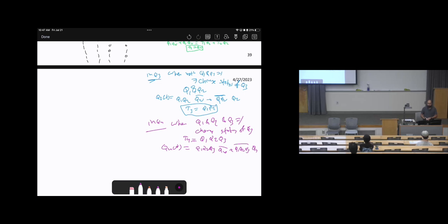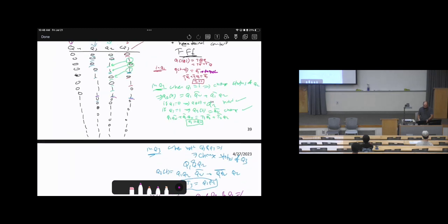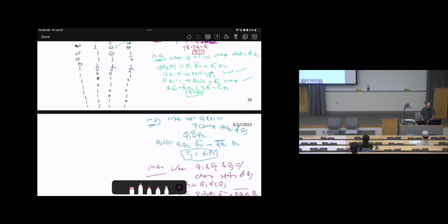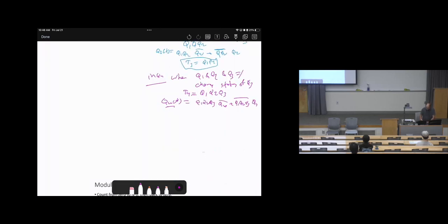Okay, so what else? How can I draw my design? Now, I already assigned all of these four. Now, I need to make my design. Again, it's based on 4 T flip-flops. So let's draw these 4 flip-flops as shown here. Here is first one, second one. Let me make some spaces. Second, third, fourth. Now, I'm going to assume all of them are positive edge triggered. Here's clock, here's clock, here's clock, here's clock.